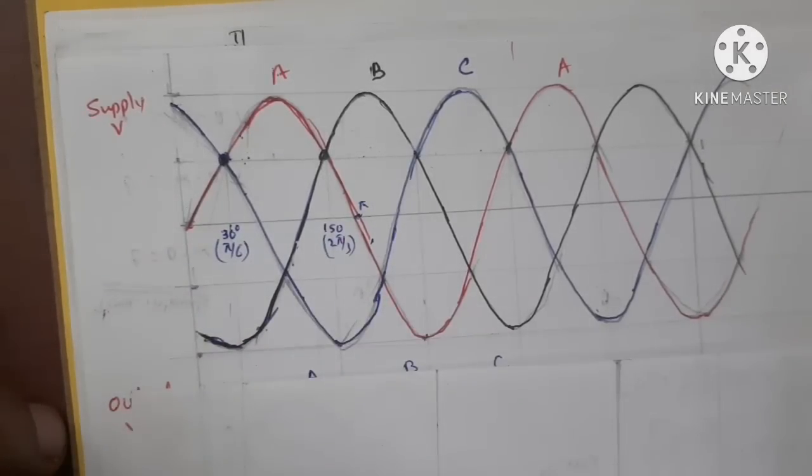Now in this case, even if the voltage at omega t is equal to pi degrees is 0, current will not be 0. The reason is because this is an RL load, it's an inductive load. So although voltage becomes 0 at omega t is equal to pi, the corresponding current will be having a positive finite value. So the current will not be 0. So the thyristor can conduct beyond the corresponding pi value. That means the voltage can be negative. The voltage across the thyristor can be negative here because the current is still positive.